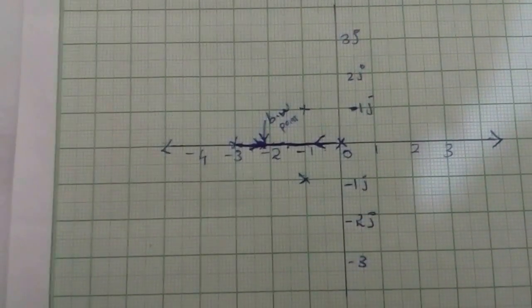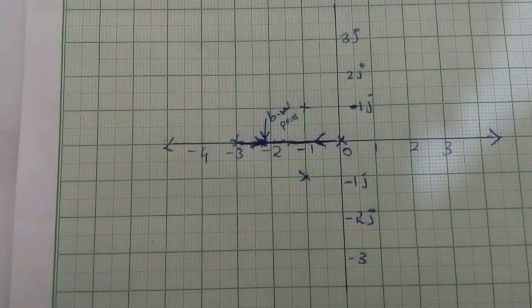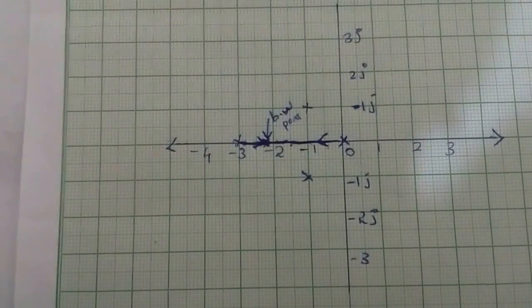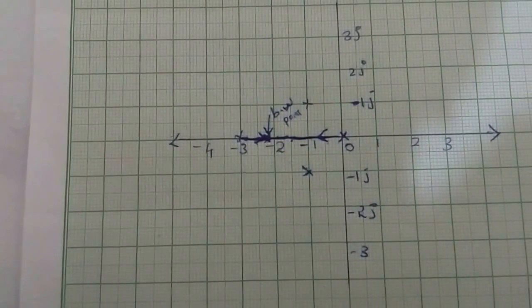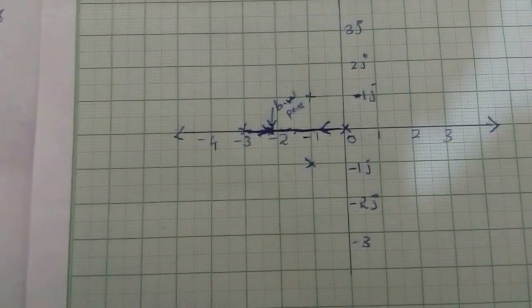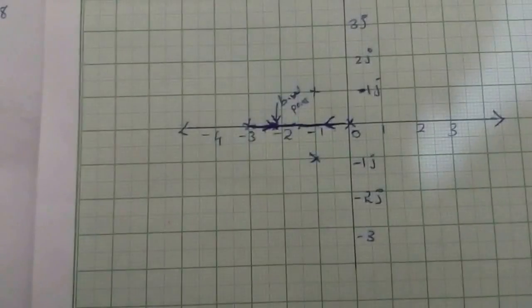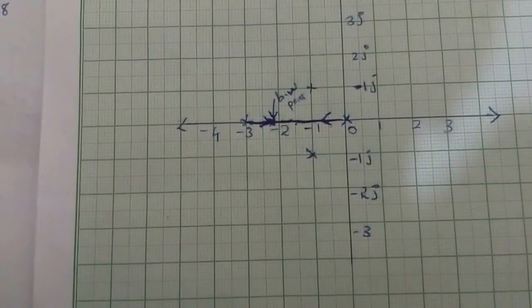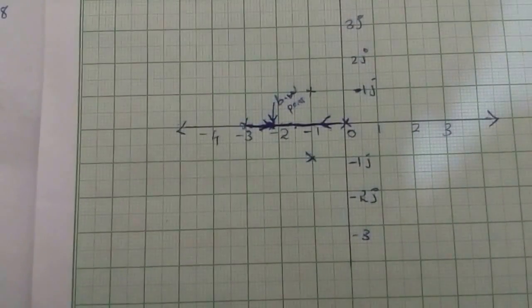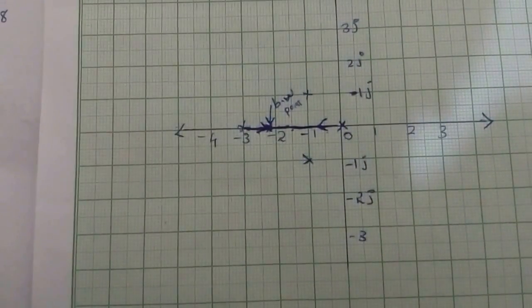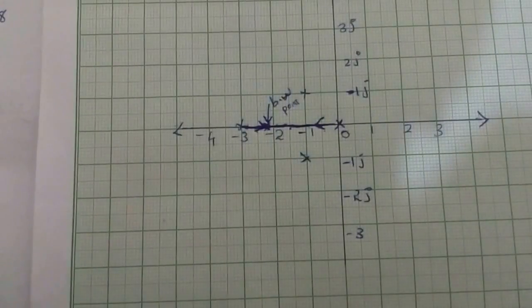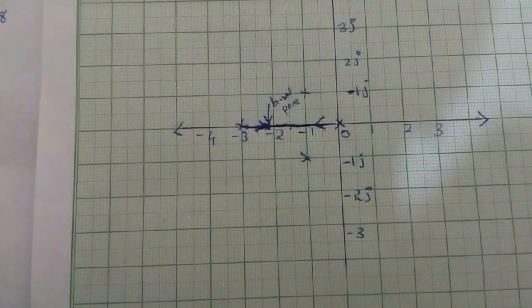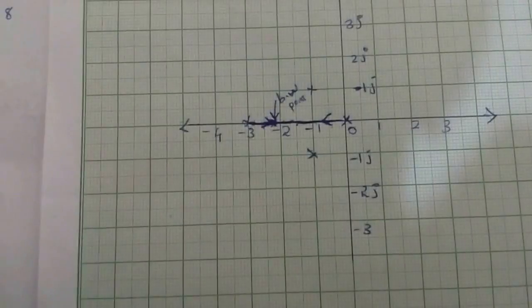In order for that, we need to find the centroid of the asymptotes. You all are familiar with the word asymptote. The distance between this asymptote and the curve becomes zero at infinity. So we need to draw an asymptote in order to draw this movement of the pole from that breakaway point.